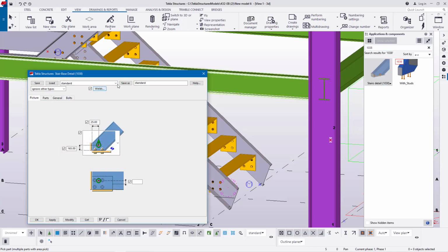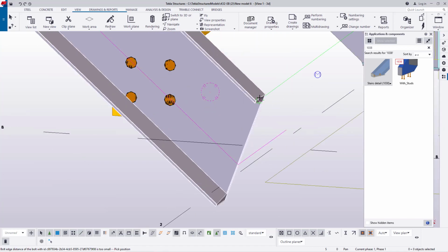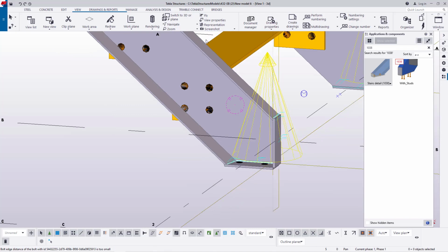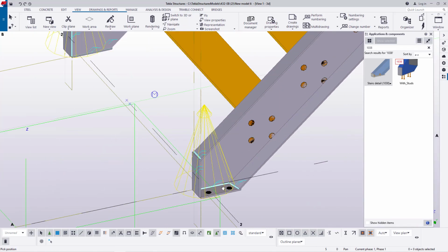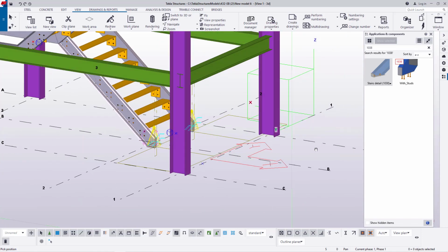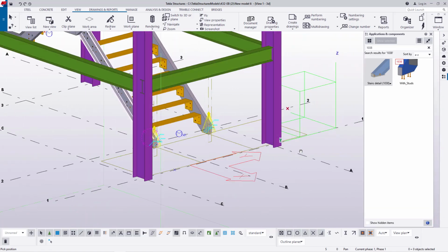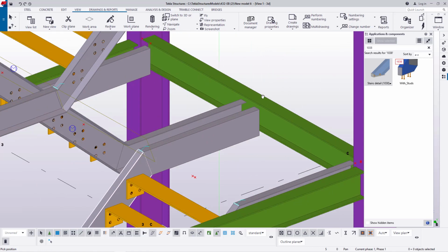Double click on that, and I'll use that. I'll not use it with studs, I'll just use the default one. I'll select on that, then try snap on that, select on this, try select on that position, and we've slightly modified that and got some holes for the bolting on top of the pedestal. Now this is how it looks, and we are still going to work on the threads. And if I zoom it close, you can see